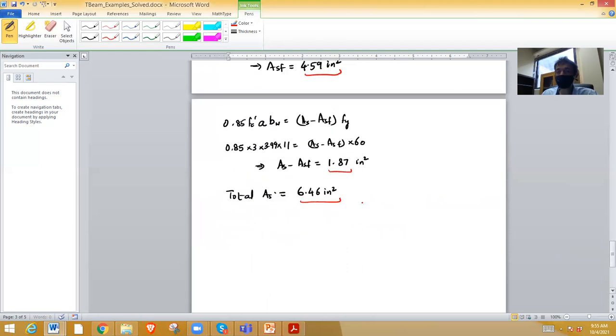Okay, so we can look up how much steel we need. Usually in a T-beam it cannot fit in one layer, so usually we need to provide two layers. Remember, we went through all the rebar spacing requirements. We need to make sure we are over the minimum spacing, and the maximum spacing usually will be fine. So put in most likely two layers, and then we redo the analysis. Make sure phi Mn is greater than Mu.